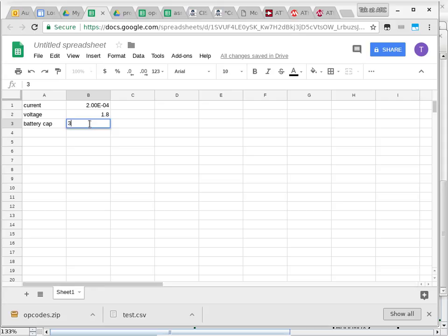So now the question is, do you want to count by hour or do you want to count by seconds? Because if you want to count by seconds, you have to multiply this 3 by 3600, which is the number of seconds in an hour. But let's say we just want to count in hours. Trust me, hour is fine. Okay. So now the question is the duration. How long can this battery, which has 3 amp hours, power this particular processor continuously in active mode? So that becomes 3, this number, divided by the current draw of the chip. It can run this many hours.